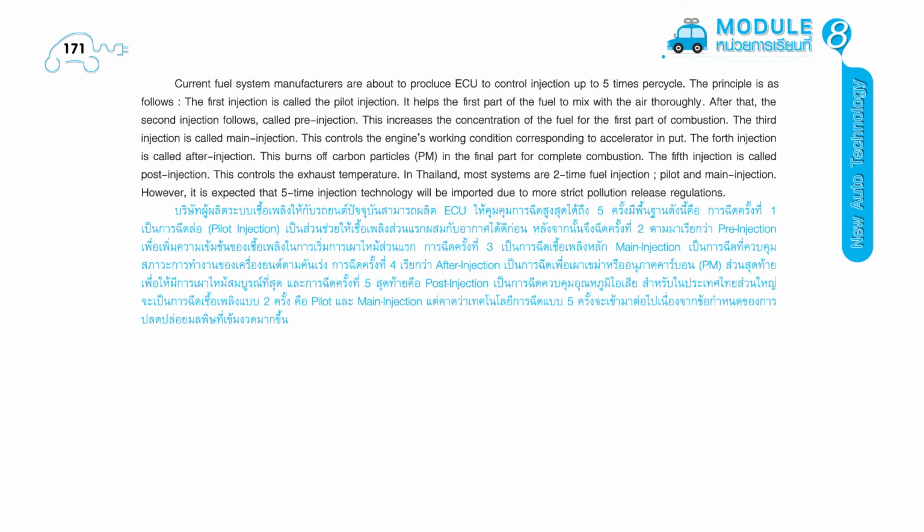Page 171. Current fuel system manufacturers are able to program the ECU to control injection up to 5 times per cycle. The principle is as follows. The first injection is called the pilot injection. It helps the first part of the fuel to mix with the air thoroughly. After that, the second injection follows, called pre-injection. This increases the concentration of the fuel for the first part of combustion.